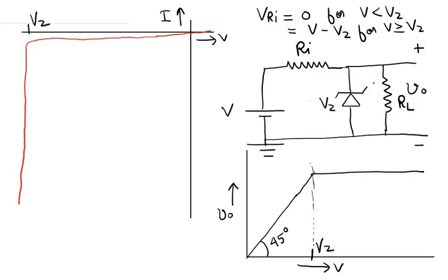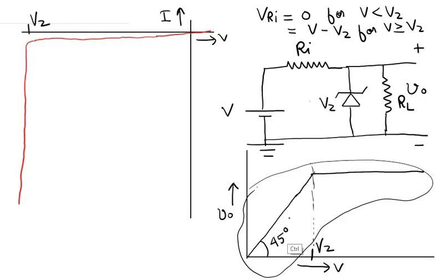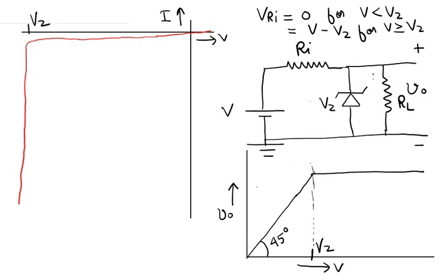Okay, so these are the cases where this Zener diode regulator is used, and as we see from the input-output characteristics of this Zener diode voltage regulator, the voltage across the diode cannot increase beyond a maximum value of approximately Vz. And this RL is the load resistor across which we want the regulated voltage, or across which we do not want a voltage higher than Vz. Or let us say RL can also be a load resistor where we want an approximately constant voltage.